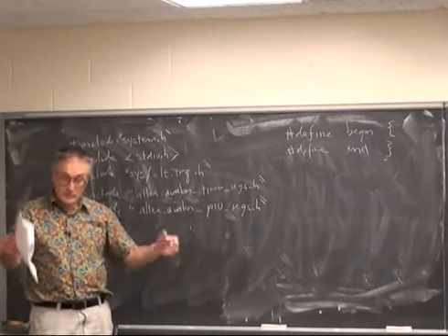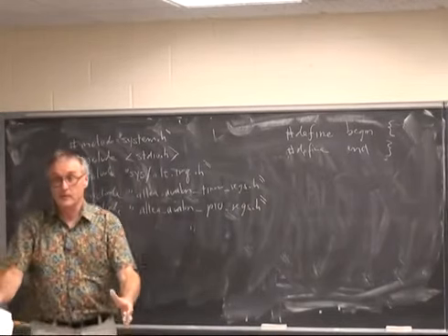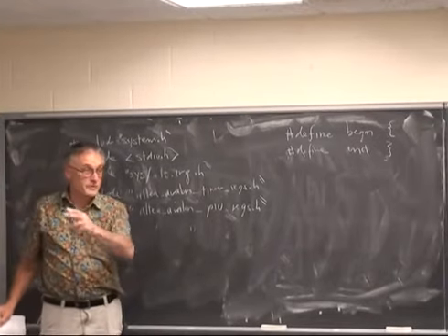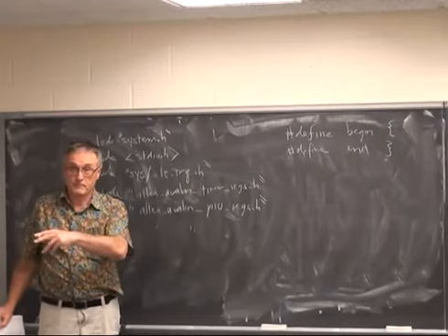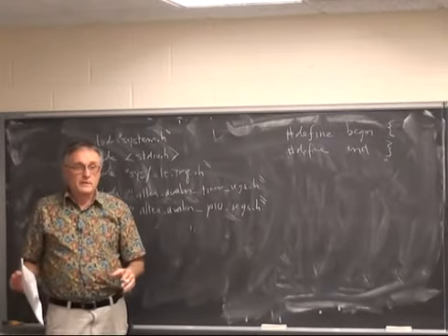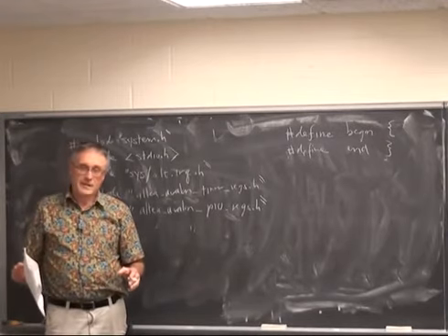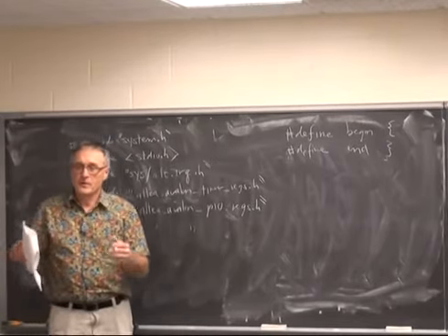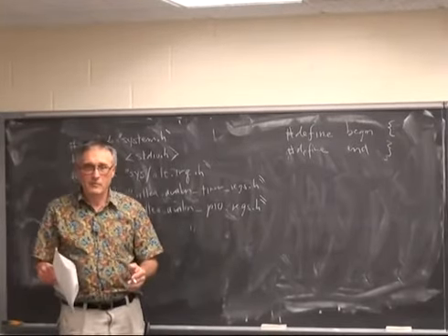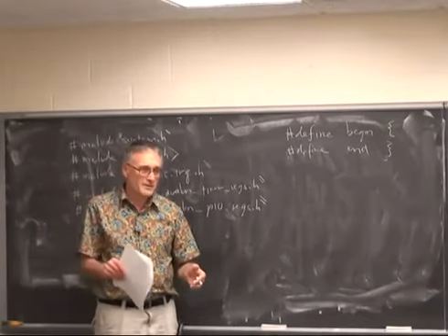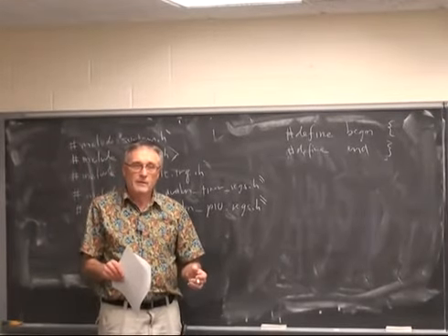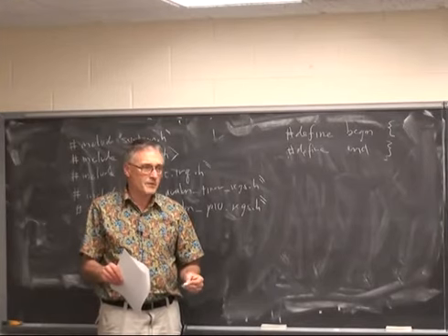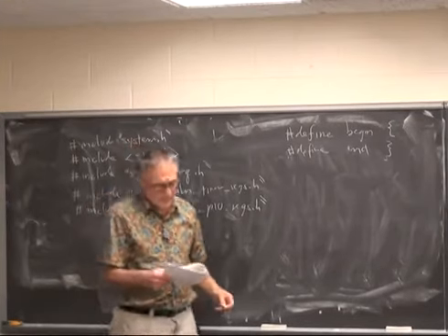It was a hardware device. It was a terminal you set on your desk. It was bigger than a modern computer, and all it did was have a serial pair of wires that went off to the actual computer. But it became a standard, an ANSI standard. And so the escape codes got ported to terminal emulators, which got ported to the device library. So when you write to the LCD, you can use VT100 escape codes.